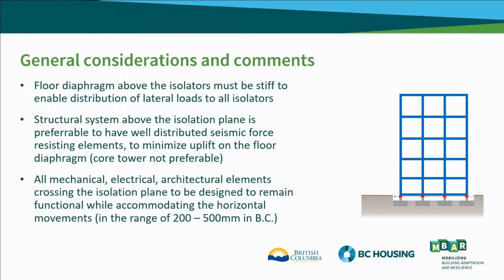diaphragm. And a key aspect: all mechanical, electrical, and architectural elements crossing the isolation plane need to be designed to remain functional while accommodating the horizontal movements. In BC, it's in the range of 200 to 500 millimeters, depending on where you are in BC.